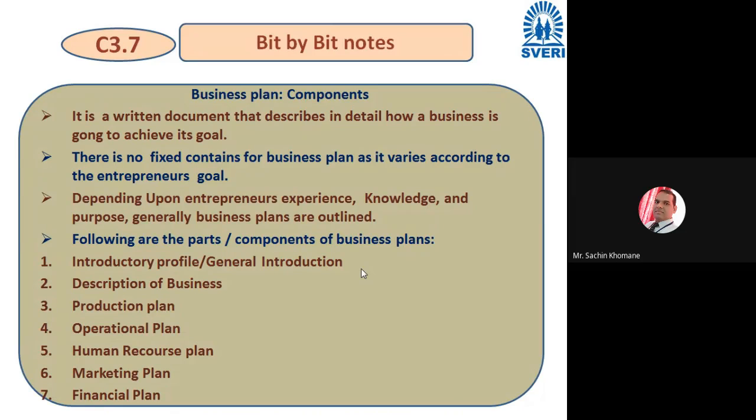So now what should be there in your production plan? You should write a production schedule. From a production schedule, what did you understand? Production schedule means when you are going to manufacture those 1000 components in that particular month, how much every day, how much in one shift. When you are going to produce how many components, that schedule you should include there. For example, you will say I will prepare 100 components every day, or within 2-3 days, like that. So that schedule should be with you.